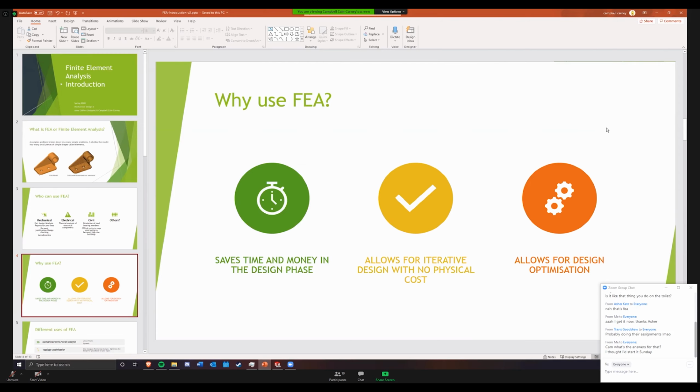So what you can do is sit down, calculate the forces, input them into the simulation software, work out where the stress is, where the stress isn't, take material away, and you can do iterative design before you actually manufacture it. Of course, you should always manufacture it and then physically test it as well, just to verify that your simulation was correct. But it saves a lot of time in terms of iterations.